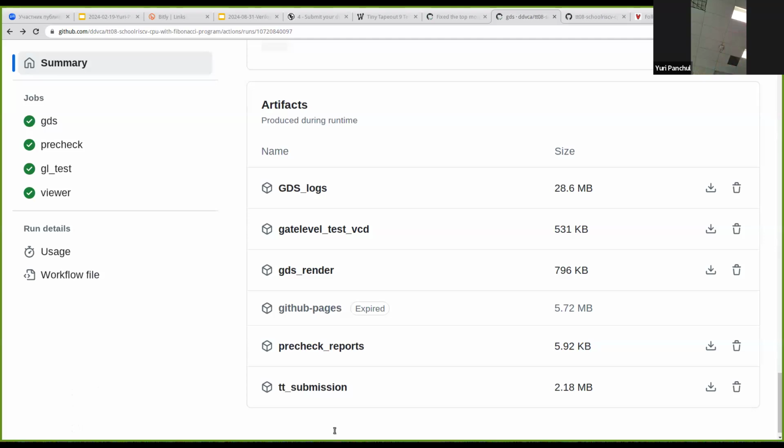Everything else we get from the website. The website tells us how many cells, how many ANDs, ORs and so on, we use for our design. And this table tells us worst slack, and all our slacks are positive, which means that we compute everything within the clock cycle and still have time left. So this is practically all we care about. We care about area, and we care about static timing analysis for our exercise. So now let's go back to our proposal.